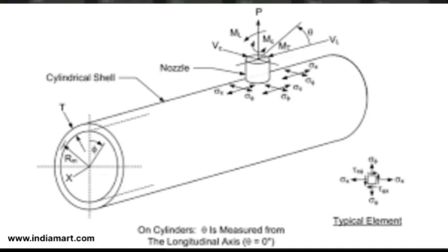Okay, so in the latest PV Elite, only the loads are taken care of? No, not only the latest. PV Elite gives a statement that generally movements will not have an impact on the support, so they will be ignored. Only forces will be considered. They will be resolved in the direction in which they are acting.